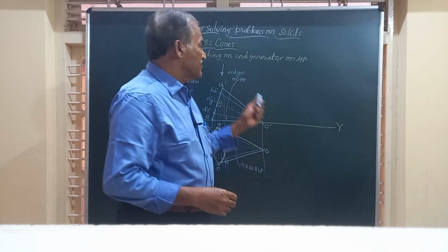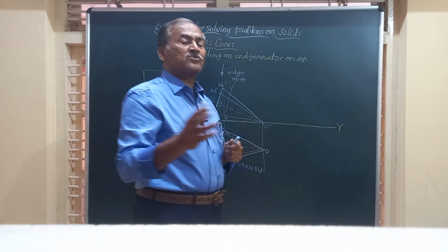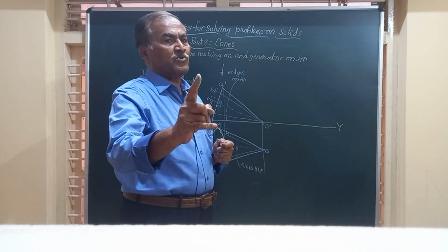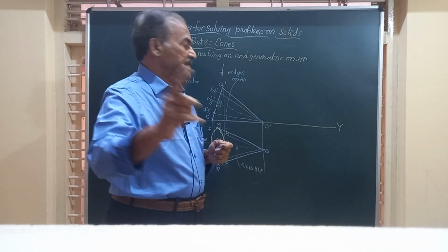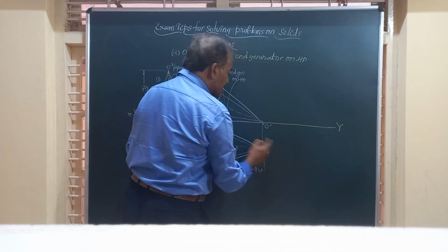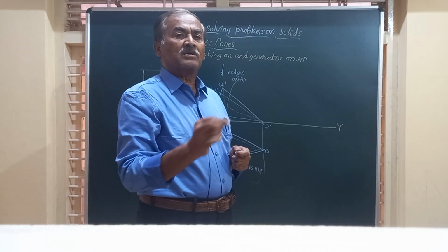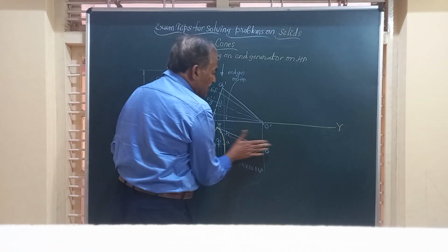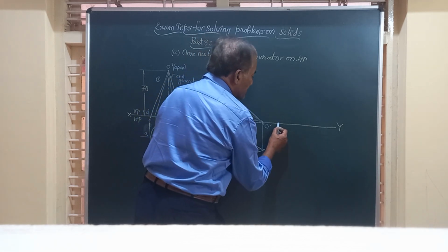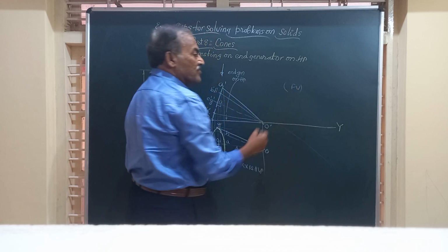Or the continuation: if they say the axis appears to be inclined at 40 degrees to VP, if you have the word appears to be inclined, redraw this figure as figure number 3, such that whatever the angle the axis makes with the VP is drawn here, and this figure has to be reproduced here at that given inclination, and we obtain the final front view.